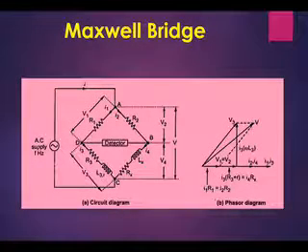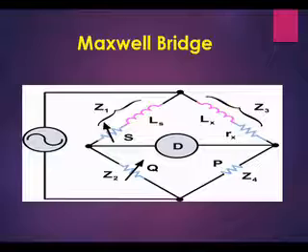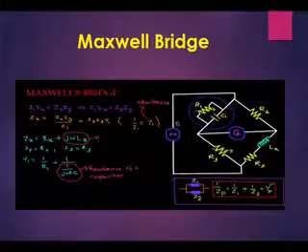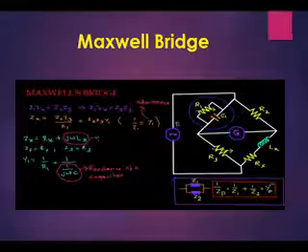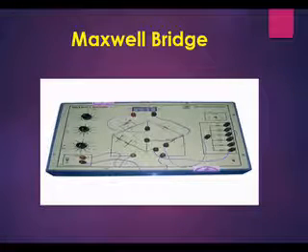The third type of bridge is the Maxwell-Wien bridge. It measures an inductor in terms of a capacitor standard. It is used to measure unknown inductances in terms of calibrated resistance and capacitance. Calibration-grade inductors are more difficult to manufacture than capacitors of similar precision. And so, the use of the simple symmetrical inductance bridge is not always practical, because the phase shifts of the inductor and capacitor are exactly opposite to each other.